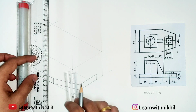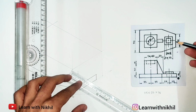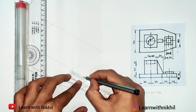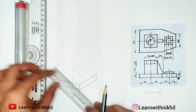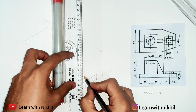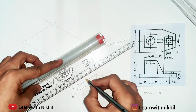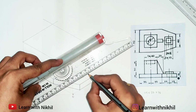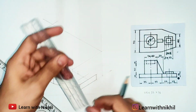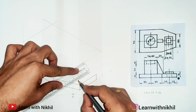So from the bottom it is 15 millimeter. So I've just taken 5 millimeter above, as previously we have drawn a height of 10 millimeter. I have to create a square of side 25. So from the center 12.5 millimeter on both the sides I have marked the point. Now same, you can draw the square here only at the bottom, and you can then project it upward 5 millimeter. So right now I am creating a square on this plane only. So here also from the center 12.5 millimeters on both the sides I am marking the point.